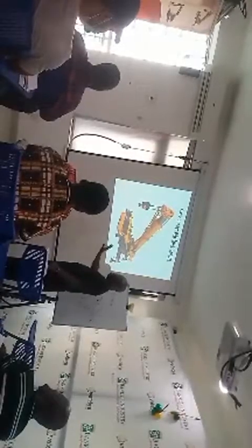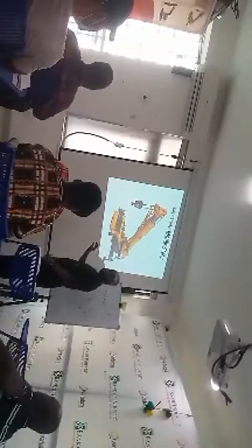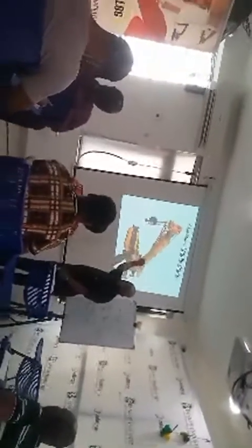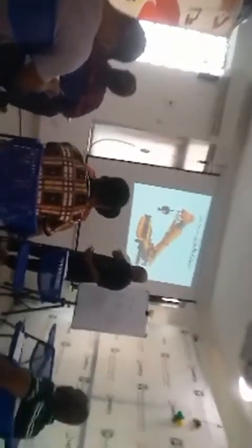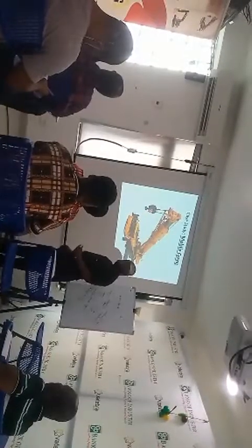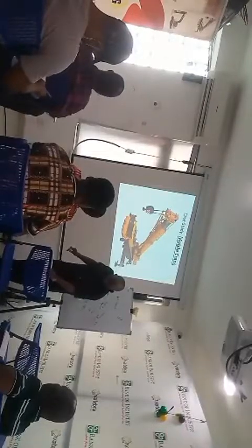So, for this particular crane or any other crane, if you use it to pick a cargo, you know the CG is permanent. Once you pick a cargo, the CG follows you with it. You understand me? And it makes it unstable. That is why some of these trailer containers are not stable: the center of gravity of the trailer has already moved up. So you must take all these things into consideration.